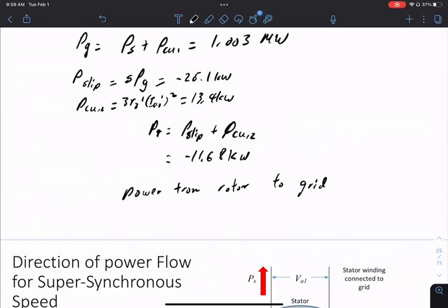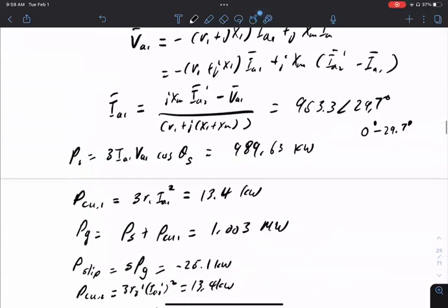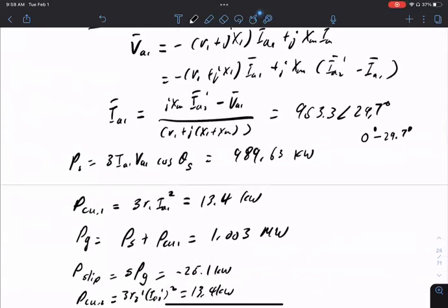As we do more calculations, you'll see this question getting turned around. Here we are given VA2 prime with this angle, and we compute everything else. Later we'll see questions where, as you said, I want this theta S to be a particular number, say 5 degrees, and go back and compute everything else. Those questions can complicate very fast.